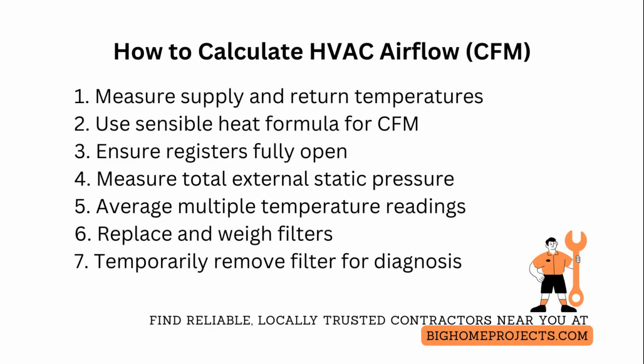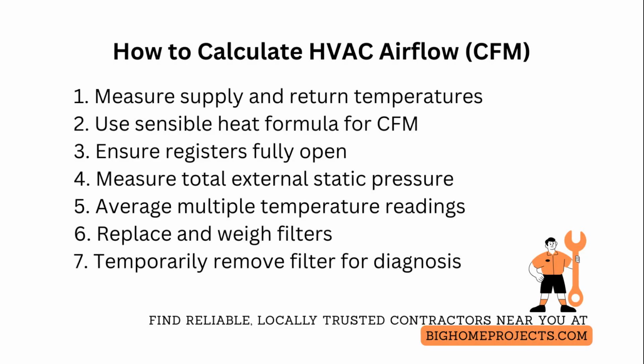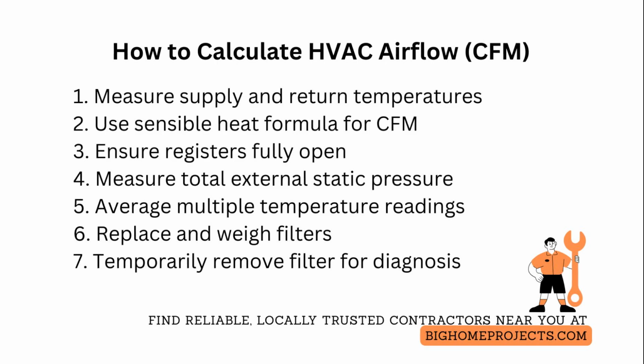Use a manometer to record total external static pressure at the blower with the system running, and subtract external from total to isolate internal pressure losses. Any reading above the manufacturer's recommended static pressure indicates likely duct restrictions or a mismatched blower.